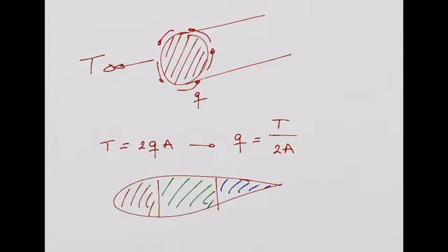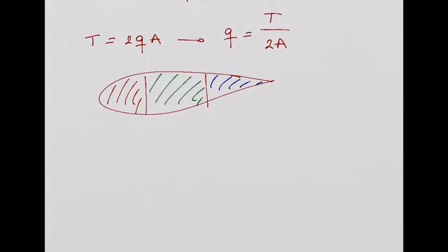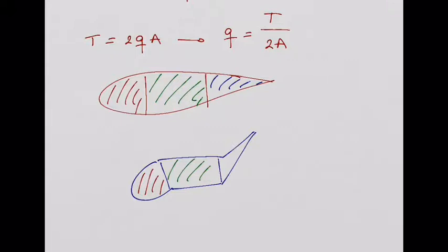And that something more we need is the twisting angle of the cross-section. Why do we need that? For example, because we cannot allow the wing to twist something like this. These three different cells that you have here cannot be such that cell 1 rotates like this, cell 2 rotates like this, and cell 3 rotates like this, right? They need to rotate by the same amount. If this happens in a real aircraft, the aerodynamics disappear, right? So that's also why we need to derive something more for torsion, okay?